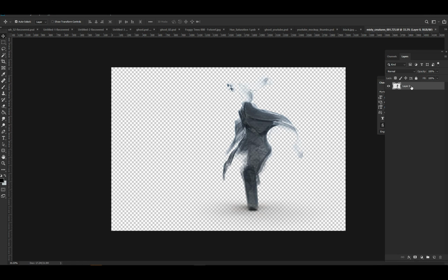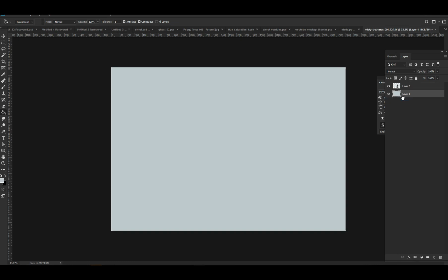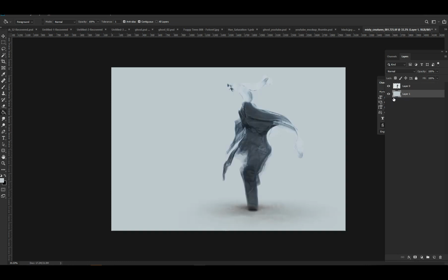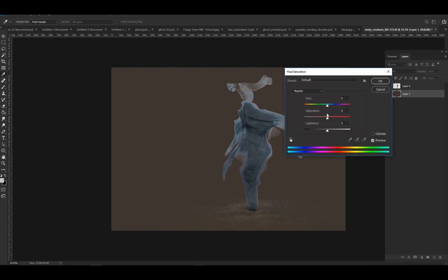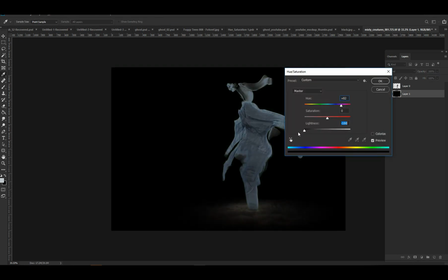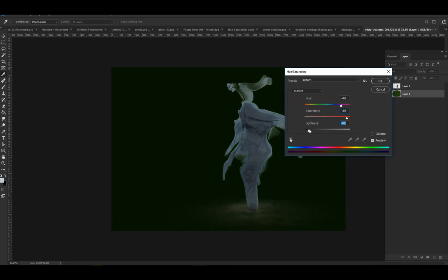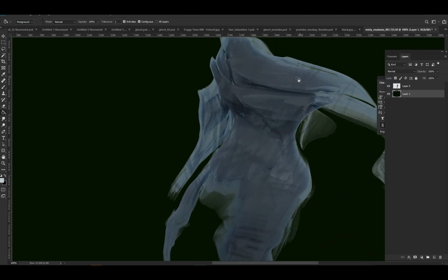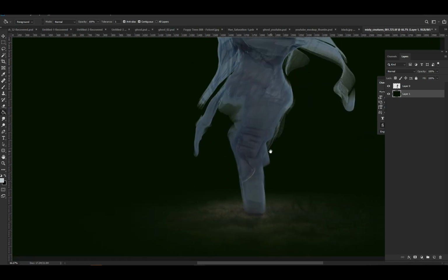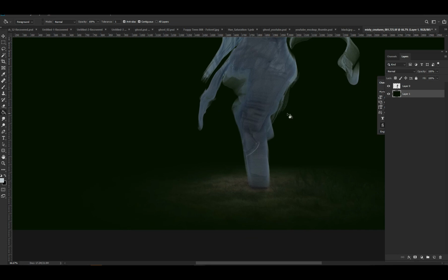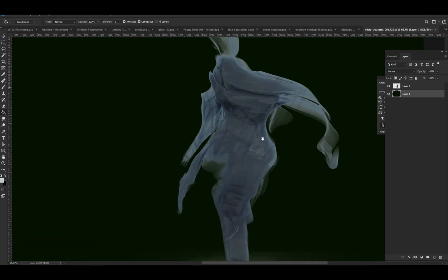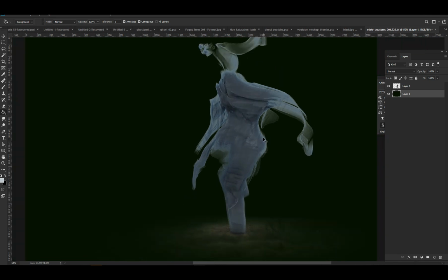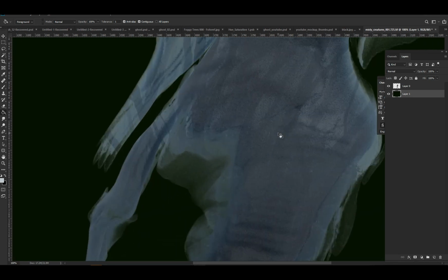And this was my final render, and isolated background. So if I put something behind, you can see how it becomes transparent. If I play around with the color, let's make it black. Yeah, usually when you render with a backplate image, that backplate starts to mix up with your render. So we can see the branches of the trees from the photo show through. Even the shadow picks up the ground color, and it's a little bit annoying, the thing that KeyShot does, but okay, there's not much you can do about it.